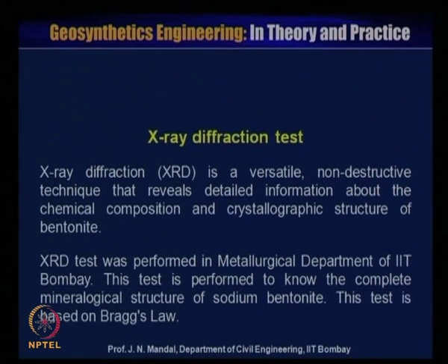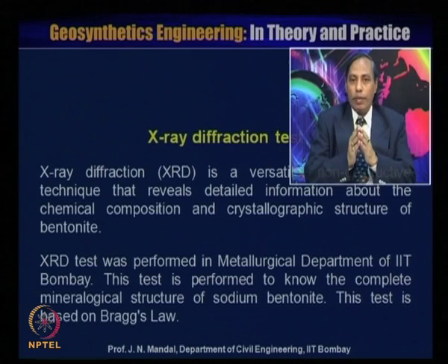Next, the X-ray diffraction test. X-ray diffraction is a versatile, non-destructive technique that reveals detailed information about the chemical composition and crystallographic structure of bentonite. The XRD test was performed in the metallurgy department of IIT Bombay. This test is performed to know the complete mineralogical structure of sodium bentonite. The test is based on Bragg's law.